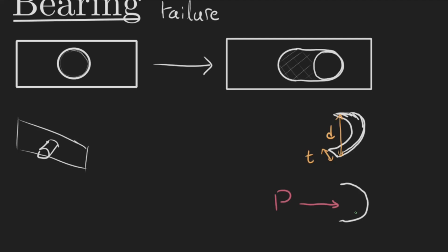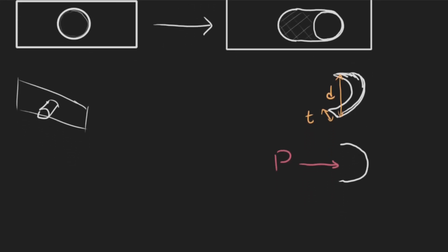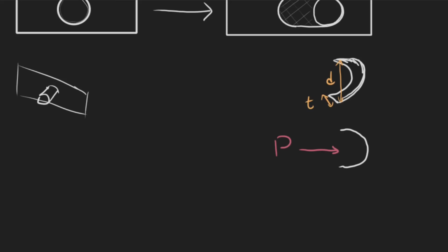And now actually examining the normal stress of this would be pretty difficult because it's not all perpendicular, right? So like right here, we would just have a direct P over A, but here there would technically be almost no normal stress at the top or the bottom. Here there would be a little bit more, and it would be maximum right here. And the book basically says that it's close enough to approximate this as just a rectangular area. So basically we're going to assume that the area is close enough to a rectangular area taking this load right here, P, to where the error is negligible, right?